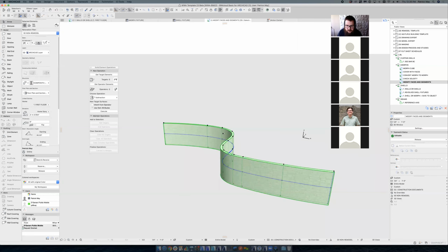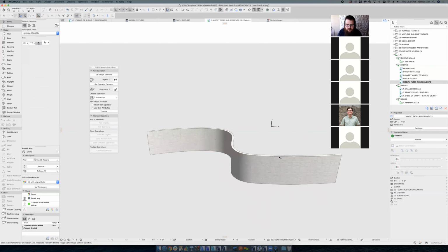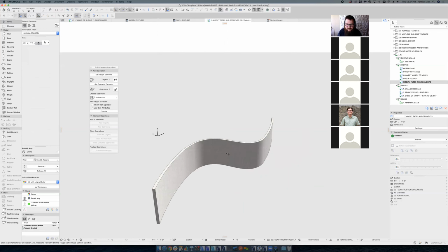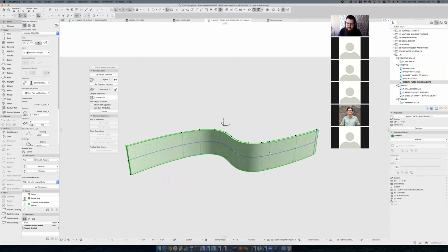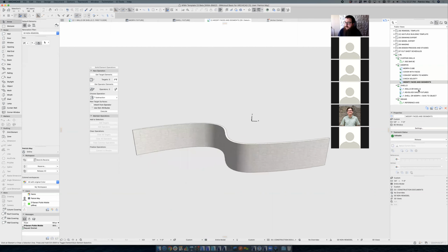And you can see that there are still those nodes there, but I don't get those vertical lines. They don't necessarily tile out all that great, and I was just noticing right before the presentation that this one for some reason changes the orientation of that surface, so it might be something that we explore a little bit deeper if this ends up being used in projects. But it was a tip that I picked up earlier this week that I thought might be good for everybody to be aware of and maybe try out on your project site models if it becomes applicable. So that's shells versus walls.